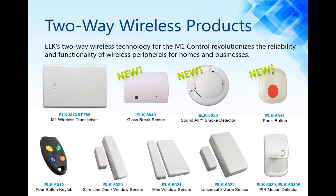Well, for instance, let's take our 6050 smoke detector. This is a wireless smoke detector that has a built-in sounder. If this detector detects smoke, it'll send the signal to the control, but it'll also start its internal sounder. Well, when the M1 receives this signal, it turns around and sends a signal out to all the other wireless smoke detectors, so they all start sounding at one time.